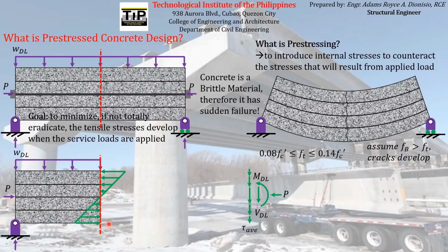And actually, the magnitude of those stresses being imposed by this axial force on this cross-sectional area is usually assumed to be uniform, just like this one, if and only if this axial force acts on the centroid of the cross-sectional area, which is the case here.